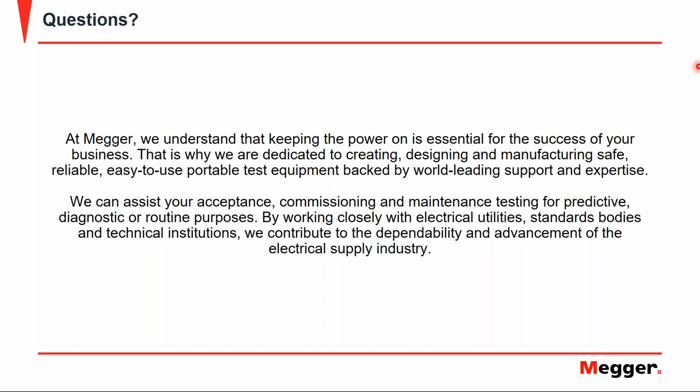All right, good question. So there are ways. First off is to determine what your background noise is. Now there are ways to lower that, in terms of checking your ground connections and making sure that your high voltage connections are elevated and not close to ground, things of that nature.